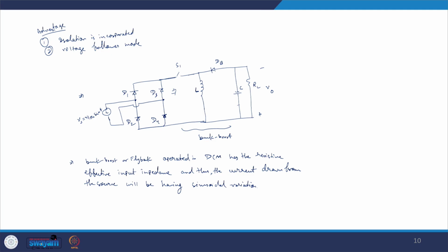So this is the way we can obtain a power factor correction converter in case we have a single phase supply. We can either have the boost PFC based power factor correction converter, or we can have the bridgeless PFC. We can also have some variation of the bridgeless PFC, but the most commonly used is the totem pole based PFC. Then we can operate them either in CCM mode or in DCM mode.